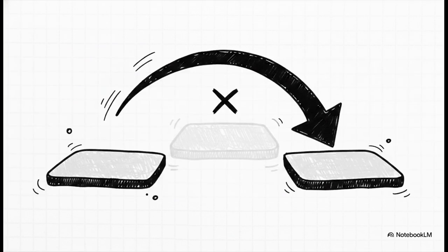Now, just a quick side note on stage 2 before we move on. The primary focus here is the transformation of any retained austenite into bainite. But if your specific cooling process didn't actually leave behind any retained austenite, which honestly happens a lot depending on your carbon content and how you quenched it, this stage kind of just doesn't do much. So for our purposes today, unless we explicitly know we're dealing with retained austenite, we can basically just bypass stage 2 in our heads and keep our focus tightly locked on going straight from stage 1 into stage 3.